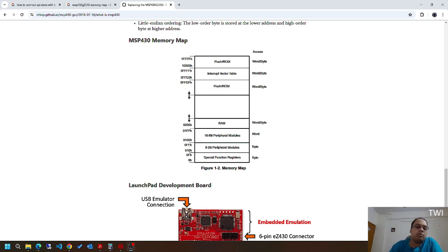The first thing we need to know is what FOTA or OTA or IAP is used for. It is a small piece of code that sometimes uses the company's own bootloader, which resides inside the microcontroller. The work of this bootloader is to load the newer version of the firmware that you push from Git or other cloud services, or over any sub-1 GHz wireless connectivity. The main intention is that you release patches, newer updates, new versions, and new implementations, and all of them have to go into the flash memory area.